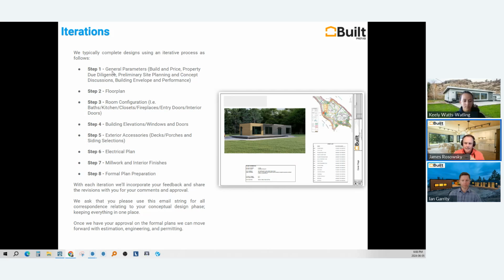Typically, I would say basically any house we're going to build will meet Step 3 just as is, if you're in BC, so the building code Step Energy Program. If you're in a municipality or somewhere that requires more energy efficiency, we'll do Step 5 homes, no problem. It just requires some differences to the way we design the guts of the building envelope, and it takes a little bit of extra planning. We have to have an energy advisor involved, and it's not a big deal, but it's something that we consider because it changes the room sizes by like an inch, and that can actually add up in the end.